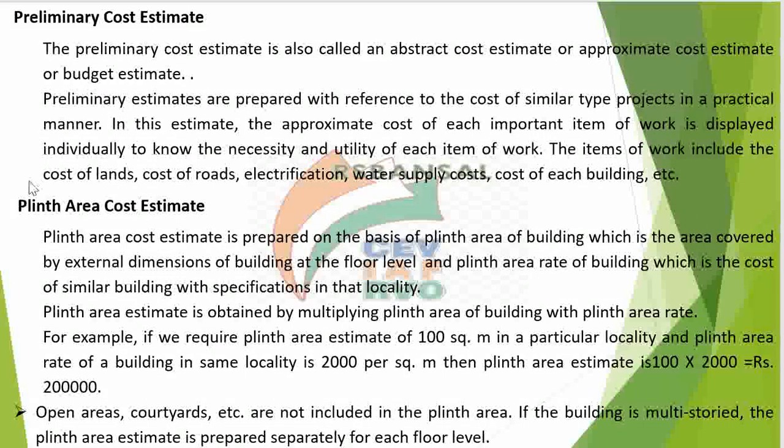And the second method is plinth area cost estimate. This is the basic method which is mostly used by the valuers while doing valuation based upon cost approach. So in this method, first of all, we calculate the plinth area of the building of which you are doing valuation.